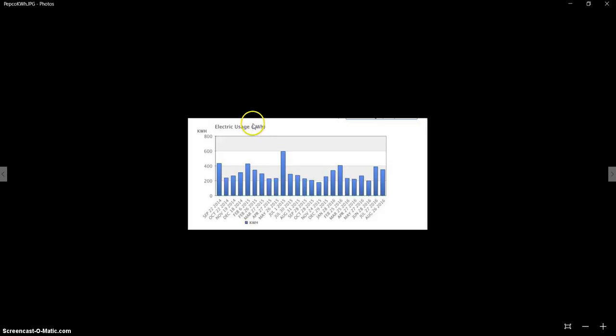What you're trying to size is your kilowatt of the system, so the rate at which you want it to produce power. As you can see, July is a high usage month for me because I run the air conditioning system. You could design the system for the worst case condition, but honestly, that would be overkill. You are relying on either batteries or being tied up to the grid to take care of any surges.